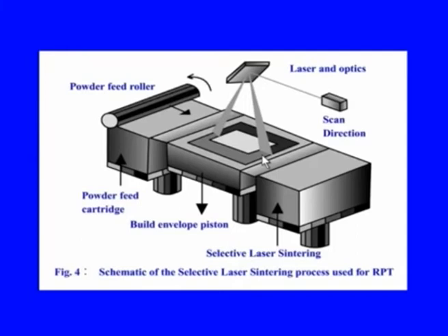They are usually loosely bonded, that means free flowing powders, and now they will be melted by using this laser. This laser power will be adjusted as per the requirement of the material. Say for example, if the powder is of a low melting point material, a low energy laser is required, low intensity of laser, that means power density should be low, and this is scanned in that area of interest.